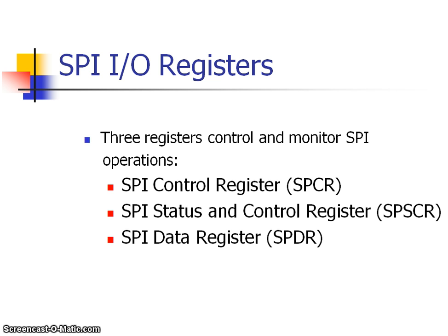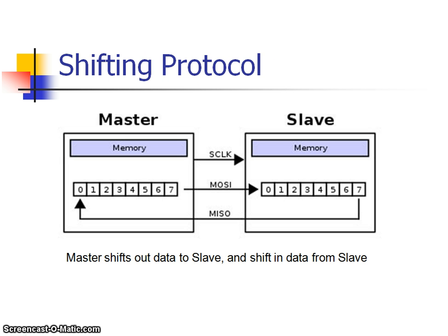There are different types of registers in SPI, mainly the SPI control register, status and control register and data register, and these three registers can be configured according to the application. To begin a communication, the bus master first configures the clock using a frequency less than or equal to the maximum frequency the slave device supports. Such frequencies are commonly in the range of 1 to 100 MHz.